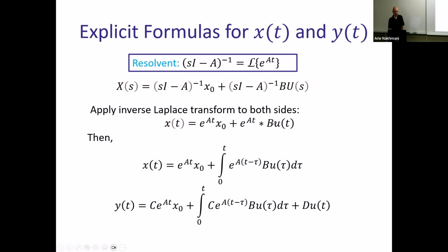And same thing, you can write that as an integral, obviously. And this will be that type of solution. This is a convolution integral plus the initial conditions state. Okay, this will be your x explicitly. People typically do not use these formulas for anything except theoretical proofs of different things. So we will not use it for anything. I'm just showing you that it's possible to write explicitly the solution of state equations as that convolution integral, right?